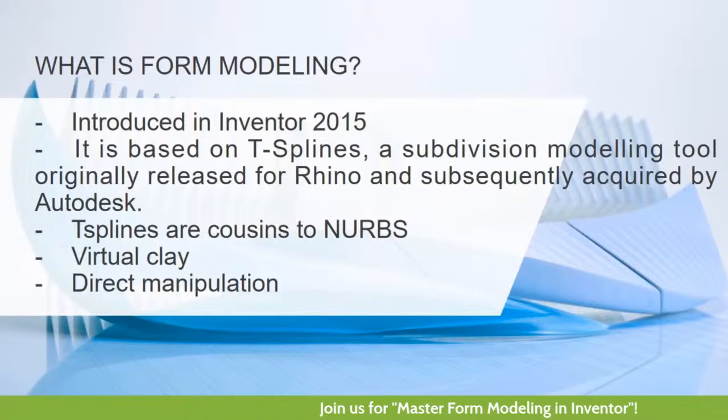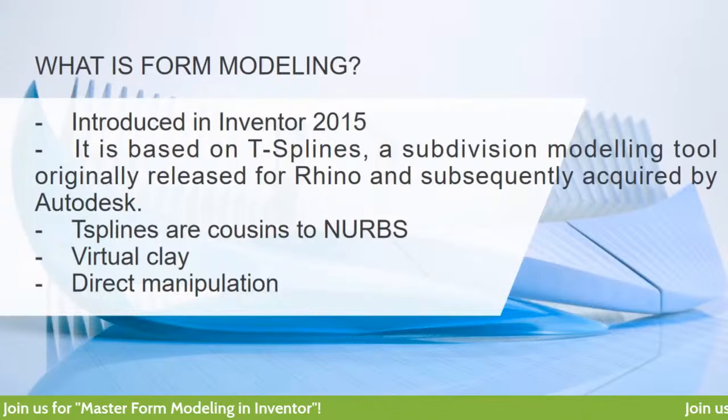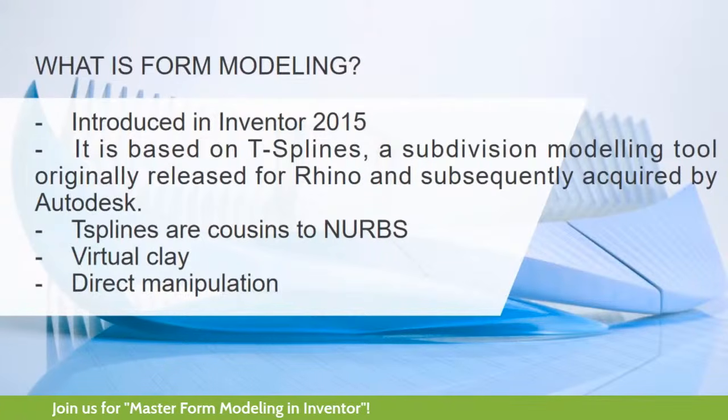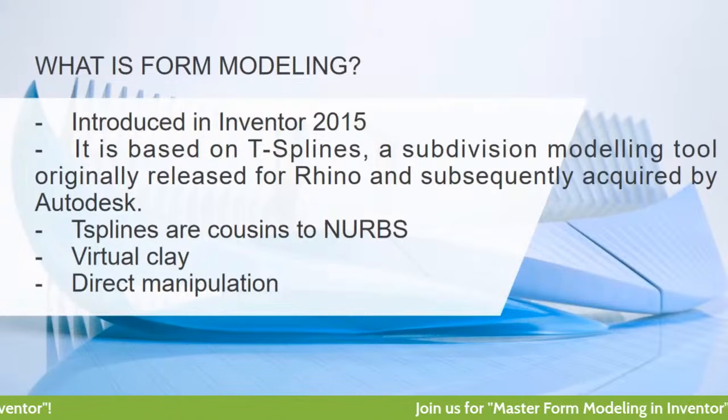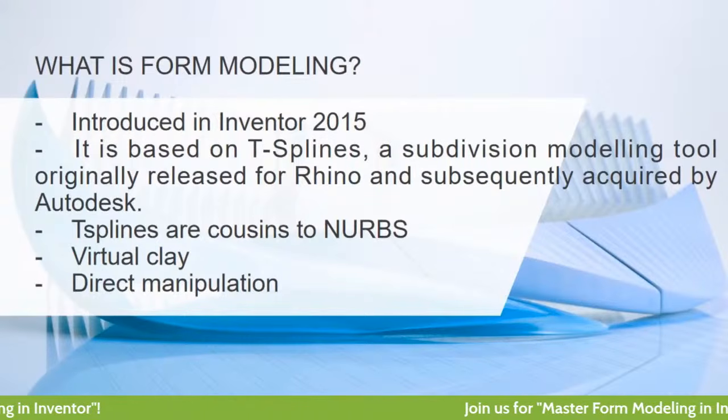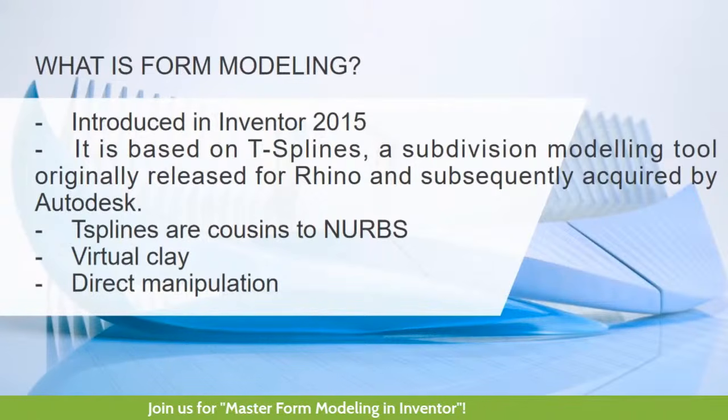Freeform modeling is a virtual clay. It is a lump of geometry that you start grabbing, pulling, twisting, and turning, which you can push corners in, very much like having that massive material in your fingers. And what you are working with is a mesh of surfaces that are connected by T-splines. Freeform modeling is basically a direct manipulation method in which the user explores new shapes by pushing and pulling points, edges, faces, as well as the entire body.